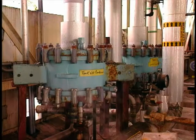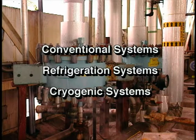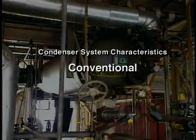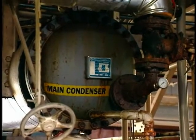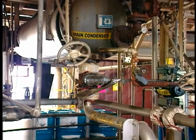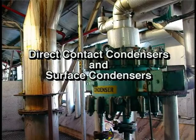Three types of condensers are used for air pollution control: conventional systems, refrigeration systems, and cryogenic systems. Conventional systems are relatively simple devices that usually use air or water to reduce the gas stream temperature to as low as about 40 degrees Fahrenheit. Temperatures as low as 0 degrees Fahrenheit can be achieved using brine coolants. There are two categories of conventional systems: direct contact condensers and surface condensers.